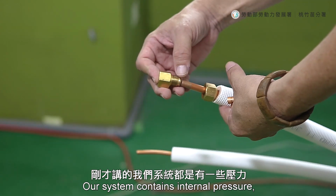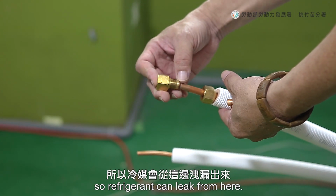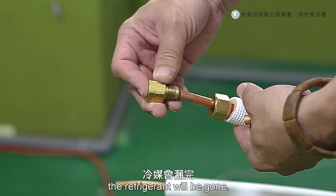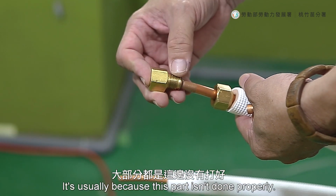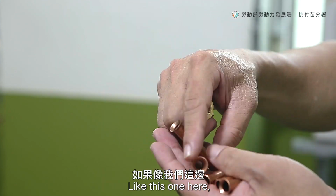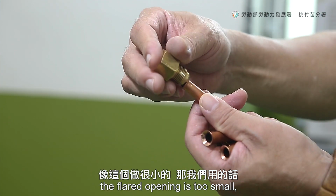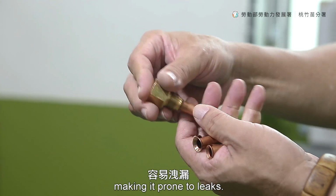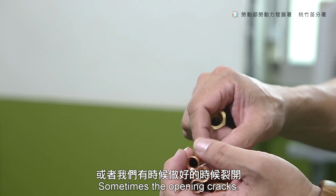Our system contains internal pressure, so refrigerant can leak from here. That's why when we buy an AC, after using it for some time, the refrigerant will be gone. It's usually because this part isn't done properly. If done properly, the flared opening will fit the jointer. Like this one here, the flared opening is too small. The area it covers will be smaller, making it prone to leaks. Sometimes the opening cracks.